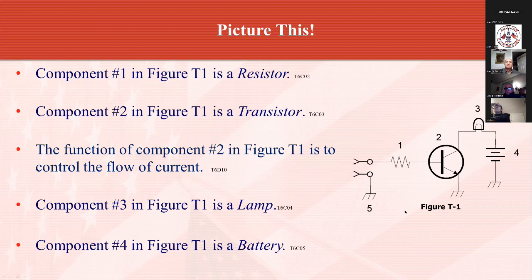How a transistor works is that if you apply a relatively small voltage or current across that point to ground, and that's from the base to the emitter, that tiny bit of voltage there acts like a switch, and it will allow current to flow from the battery up through the light bulb and then down through the transistor, and that's when the light will come on. So it's that little bit of voltage that gets applied from the base to the emitter, and that's where the 1 is and where the arrow points out of the transistor. A tiny bit of change in voltage there will allow the larger voltage along the back side of that to flow, and it'll make the light bulb come on.